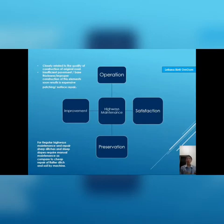Highway maintenance is closely related to the quality of construction of the original routes. Insufficient pavement, bad thickness, and improper construction of these elements soon result in expensive patching and surface repair. Shoulder care becomes a serious problem where narrow lanes force heavy vehicles to travel with one set of wheels off the pavement.